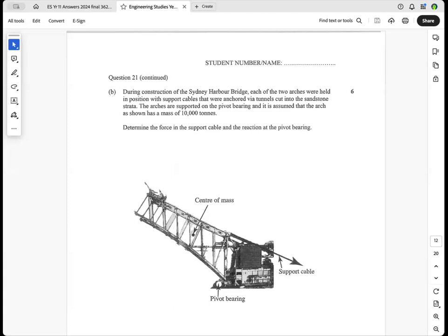Because it was a massive cantilever here, they had to have high tensile cables anchored down here, and in the 20s and 30s, they didn't have sufficient strong anchoring devices, so they had to build a tunnel which anchored these quite significant cables. So they went around, and one arch supported the other arch through the tunnel.